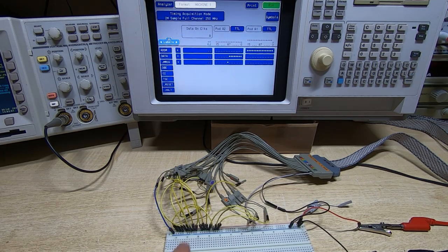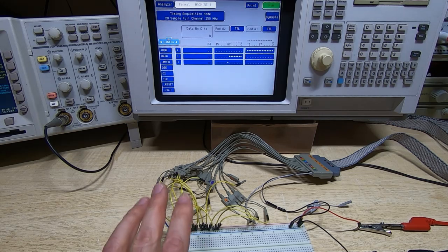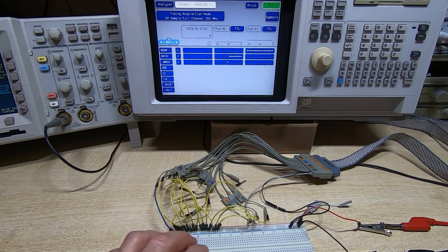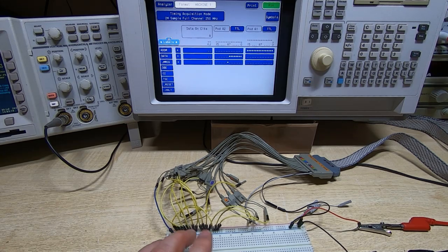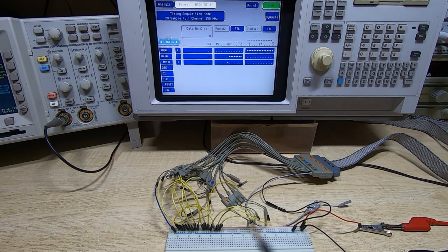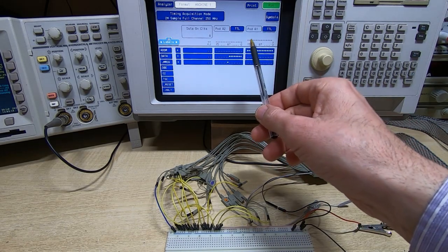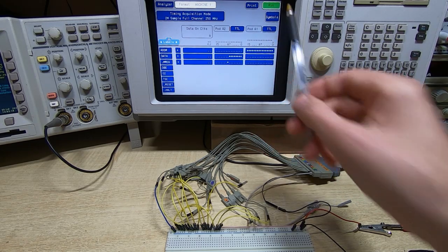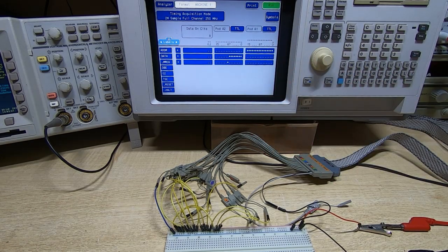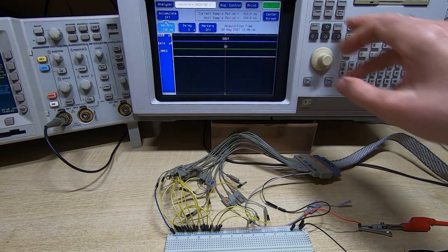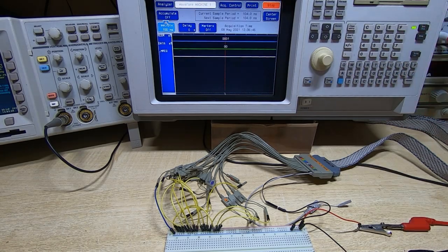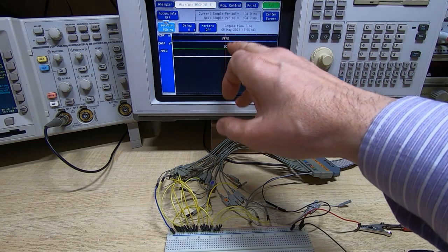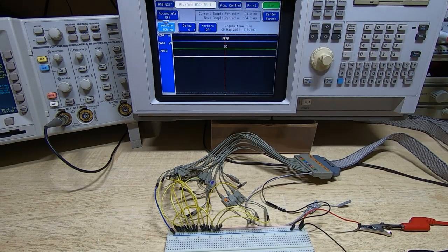Okay, so I've reversed all the connections, so this is how this same data value of 1 would be represented on the actual bus of a PDP machine, which uses negative logic. And if we look on the analyzer, you'll see that all the high order bits are showing as high and bit 0 is now showing as 0. So if we rerun this capture, we're now getting a value of FFFE, and obviously that's not really what we want. We want it to show a value of 1.